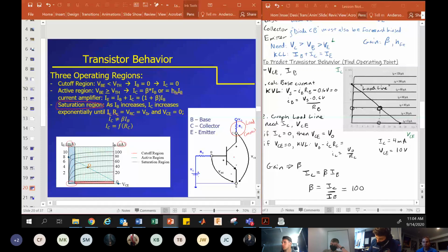You can use it for that. We're going to use it to turn things on and off. Yeah, we're going to use it as a switch. So say we're turning on a motor. Do I want the energy that I'm using going into the motor, going into the transistor, going into both, going into neither? The motor? Yeah, we want to turn a motor. So if I've got like a 6-volt battery, I want all that 6 volts going into the motor. I don't want it going into my switch.